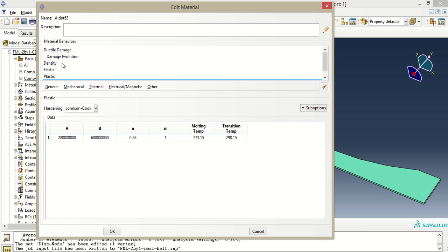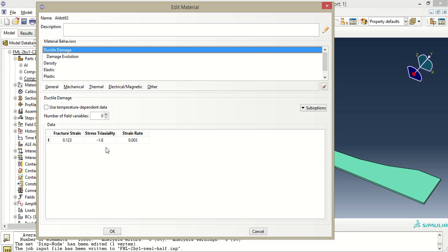So you know what these are, and I can club this with damage, Johnson-Cook damage analysis also. I have used it in combination with ductile damage, as it is much easier to implement. It requires three quantities: fracture strain, the strain at which your specimen has failed; and stress triaxiality. Now this is a very funny term. Usually it is plotted in the Johnson-Cook model. Actually, you require this at different strain rates. So stress triaxiality is an important parameter.